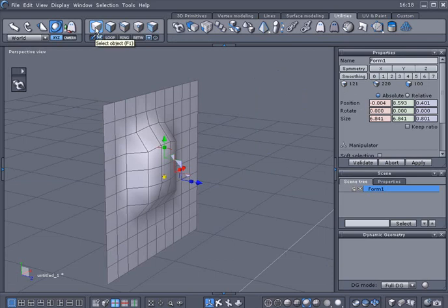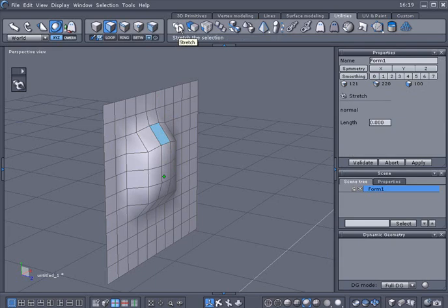Okay, instead of being in selected object mode first, let's say we're going to go into select face mode first, before we press the stretch tool. Now if I select it, as you can see, I got some options. It says for the normals. So look at the direction of the highlighted face and look at the angle that it's pointing at. So when I pull on it, it's going to try pulling that angle and direction.